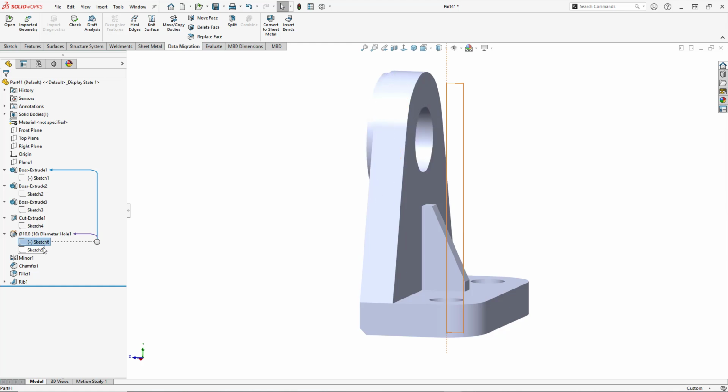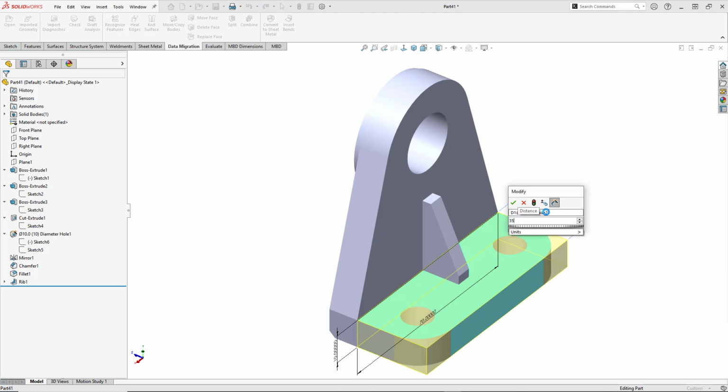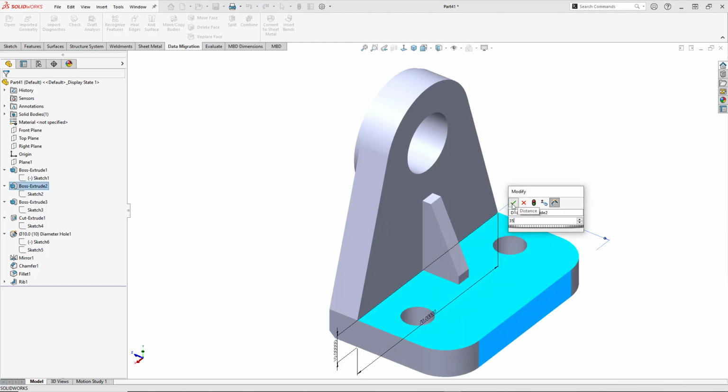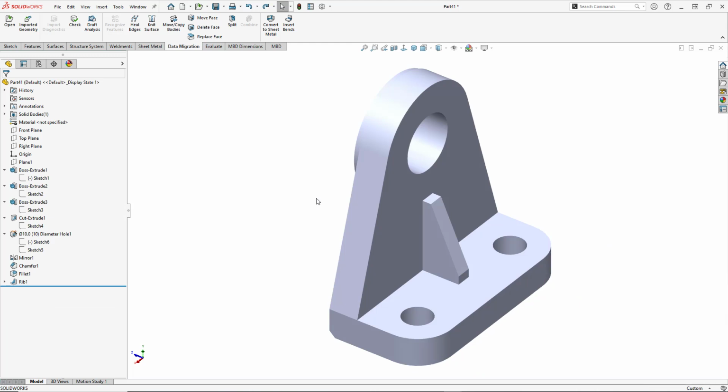Looks like we got a sketch location here. And I can see that this sketch location has been created before this fillet, which kind of defines where this hole should be. So if I were to test this theory, maybe I go in and try to change this base to be larger. And yep, as I expected, those holes don't follow that geometry. And that's the design intent I'd like. I'd like those holes to follow and stay concentric to this fillet curve here. So let's go ahead and undo that.